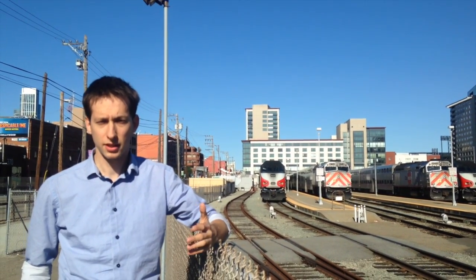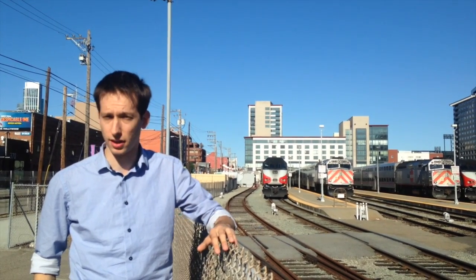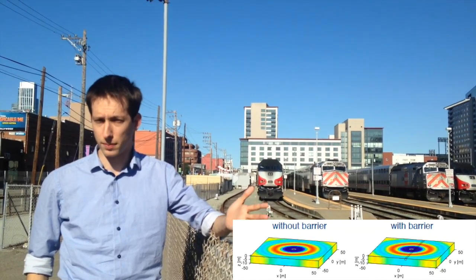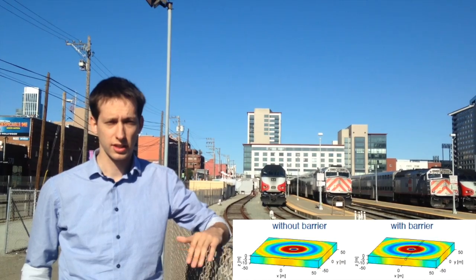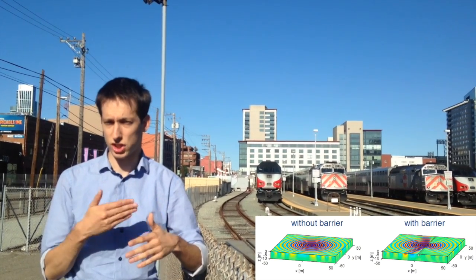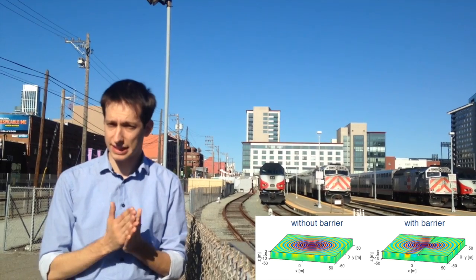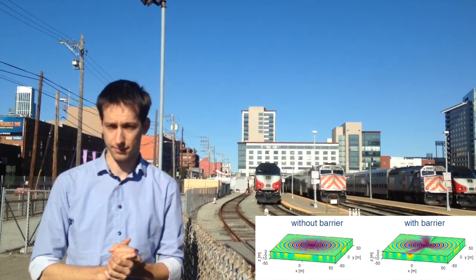A stiff wave barrier can be a very efficient vibration countermeasure, provided that the stiffness contrast between the barrier and the soil is sufficiently large. At very low frequencies, the barrier is unable to impede the propagation of railway waves in the soil, because their wavelength is too large. But from a specific critical frequency on, there are waves in the soil which have a trace wavelength which is smaller than the free bending wavelength of the barrier, and the propagation of these waves is impeded by the barrier because of its large bending stiffness.